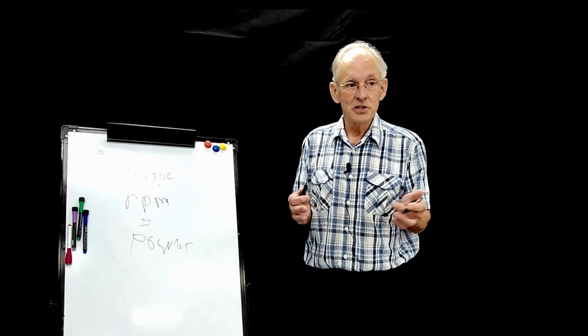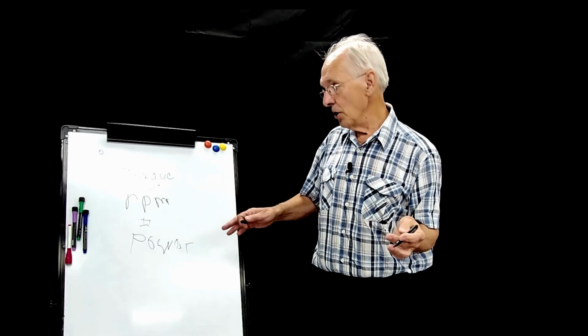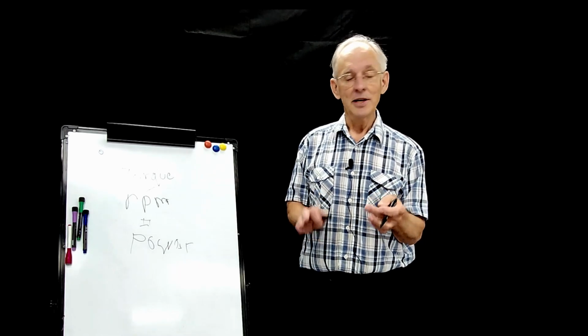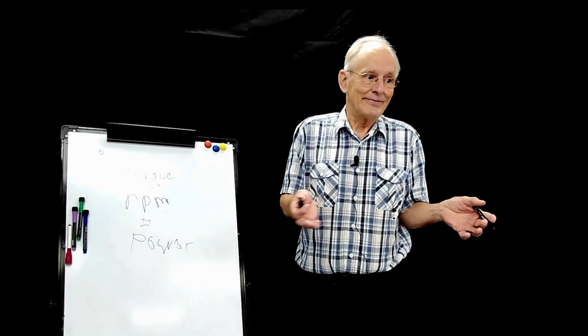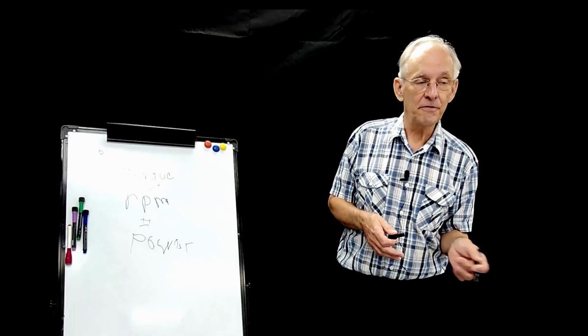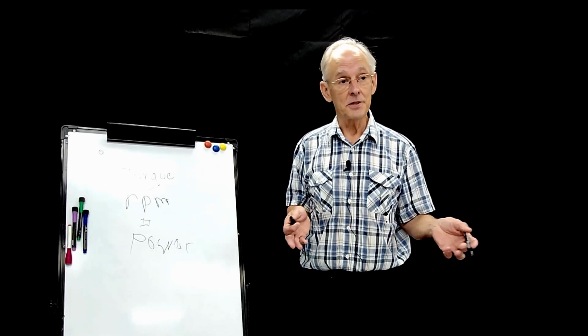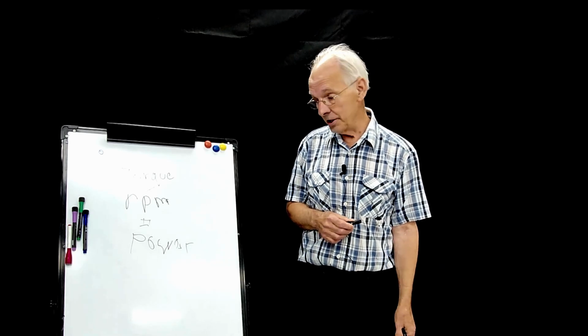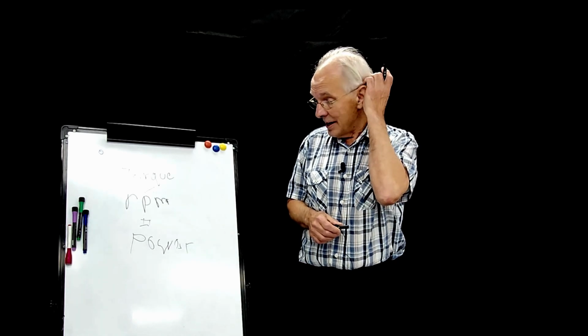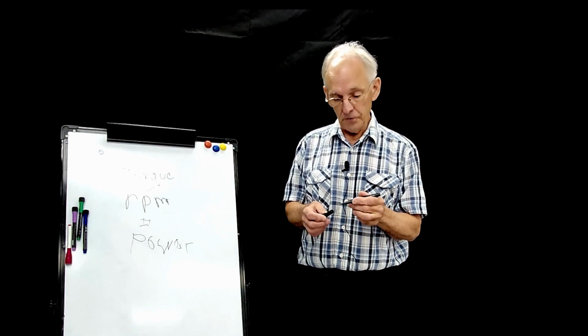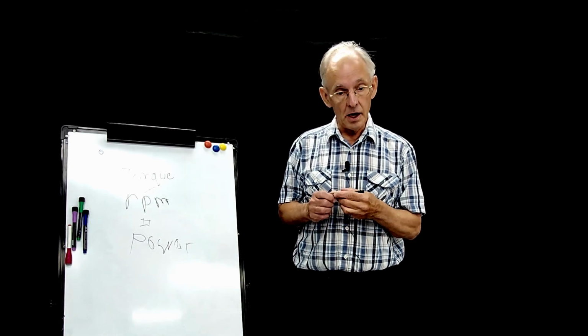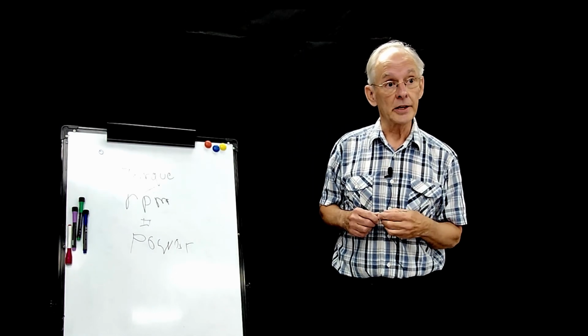But in selecting a motor, you really want to know the torque and the RPMs. The power is kind of the final element. You're going to find out how big a motor you need based on torque times RPM that you're working with. So those are the important factors that come into every motor selection.